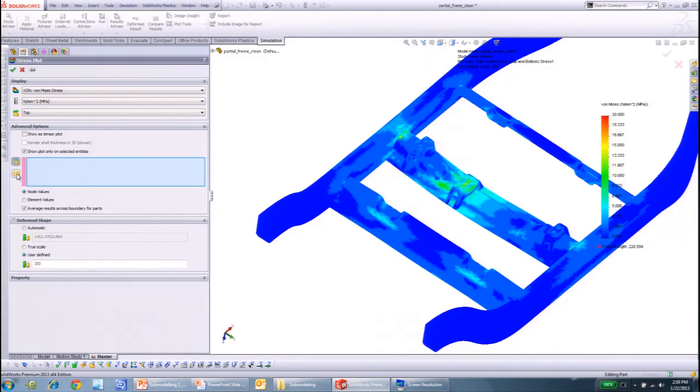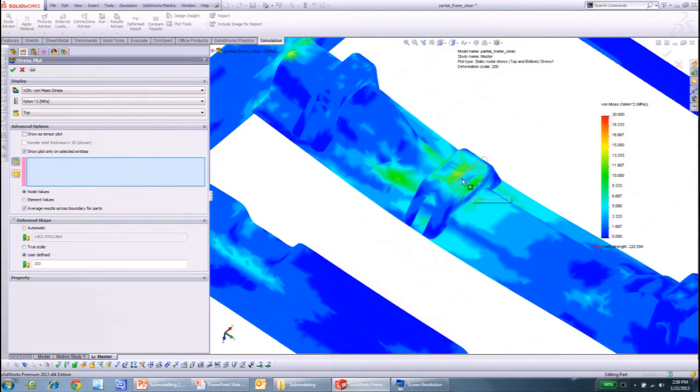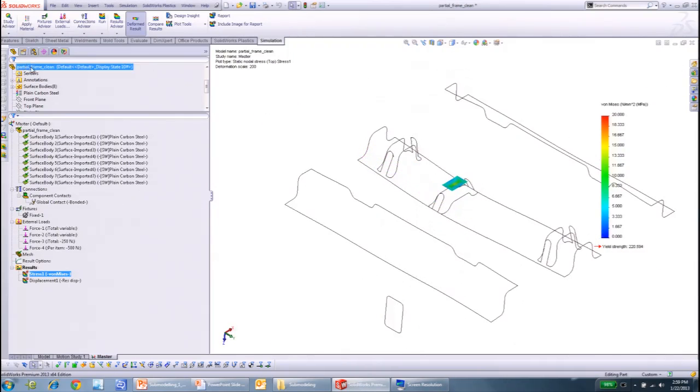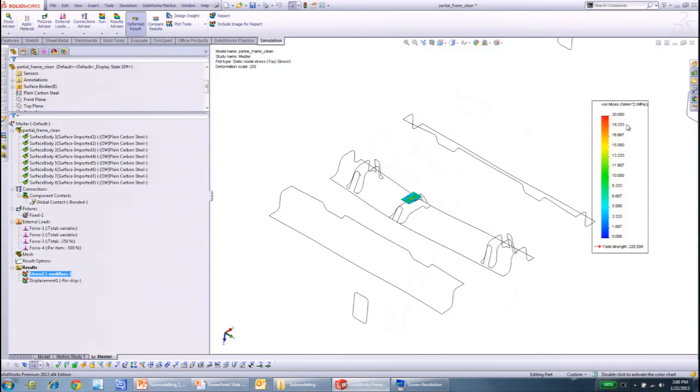In this case, it's only surfaces. I can just select faces on which I want to just see the result. And it'll just create that plot for you, so you don't have to go back to SolidWorks, hide it, show it, then come back, because all plots have now those faces hidden, so you can tailor it specific to a plot. And then you can also have the result.